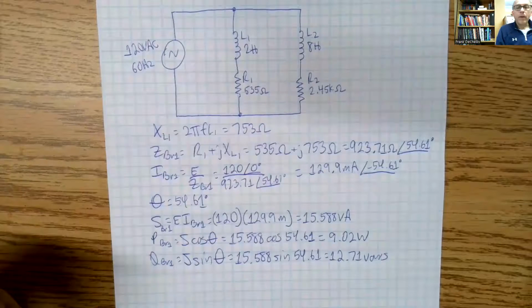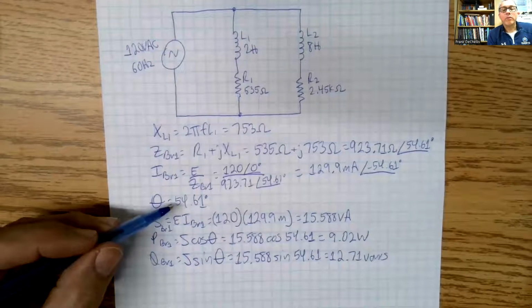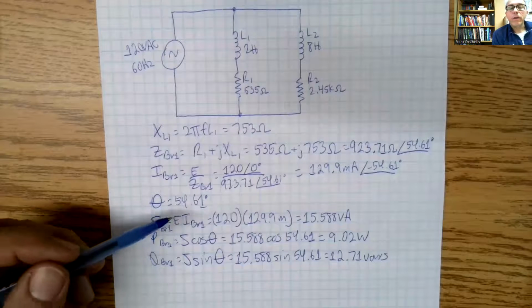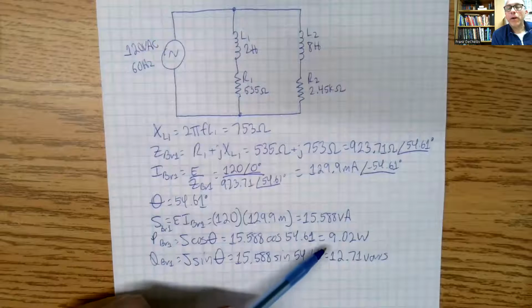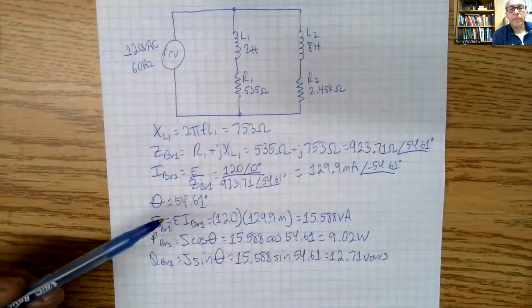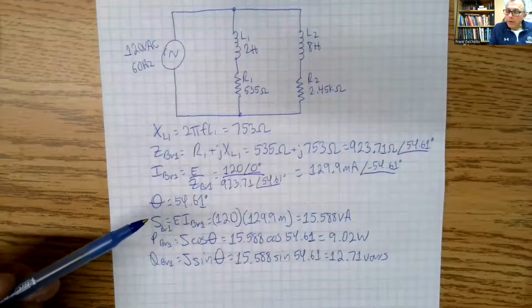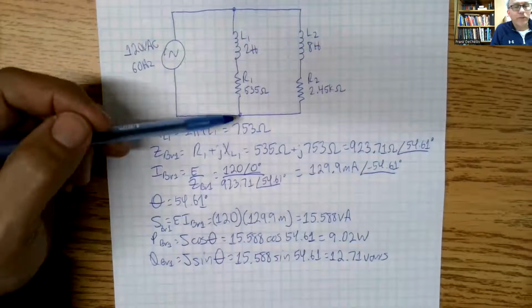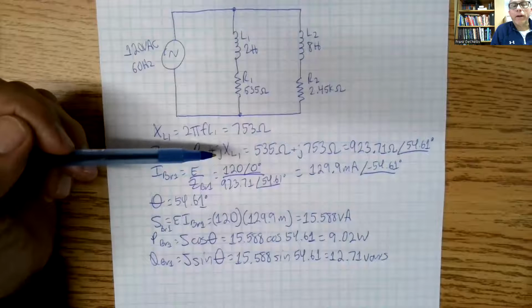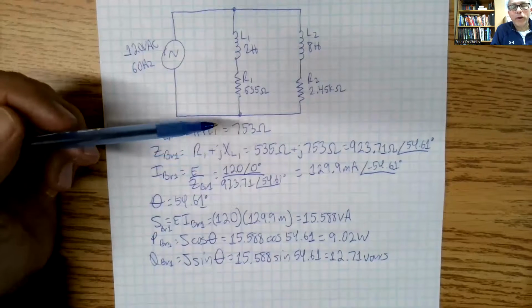Now, the fact that the angle is greater than 45 should tell us that our reactive power should have been greater than our real power. Okay, so let's correct this branch only to 0.9. Let's just correct that branch to 0.9.